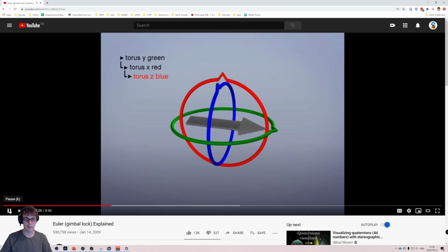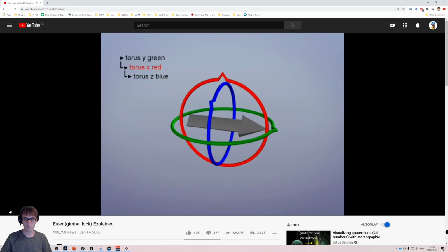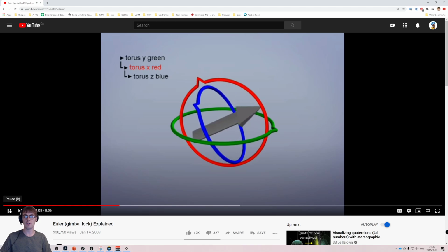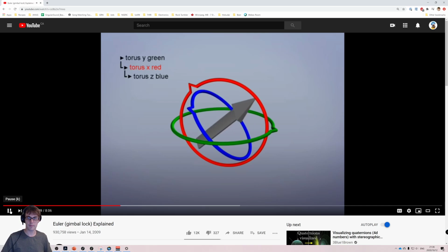X is second in the rotation order, so it'll affect Z below. And see how Y stays still, because it's at the top of the hierarchy. That's a visualization of how you're actually modifying the coordinate system lower in the hierarchy. Now here's where things start to get interesting. If we continue to rotate X in the middle of the hierarchy, it'll cause Y and Z to align.